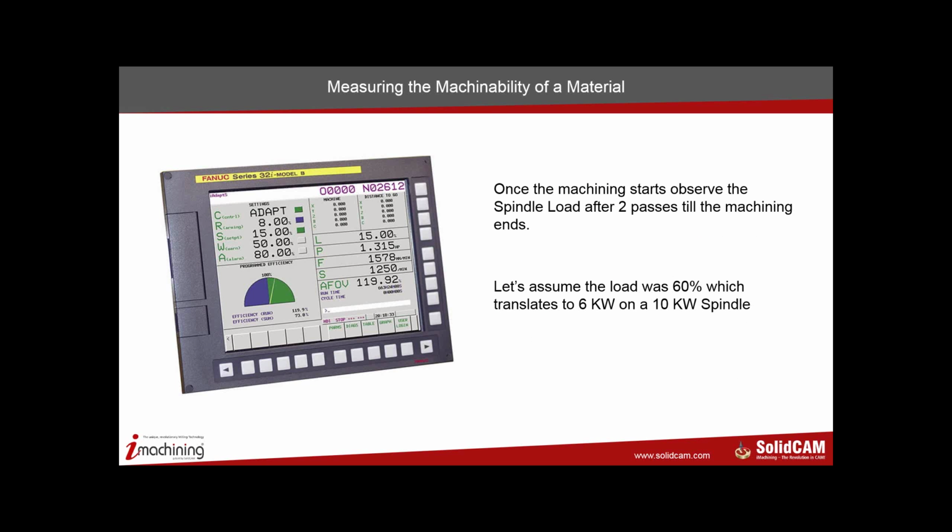and we start cutting. Now the cutting has to be in real world conditions. So if you're going to use cooling, you have to use cooling. If you're going to use fluid, you have to use fluid. Everything has to be as though you're machining the exact part, exact production.